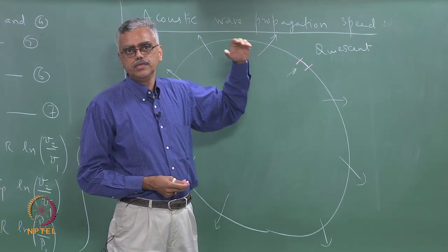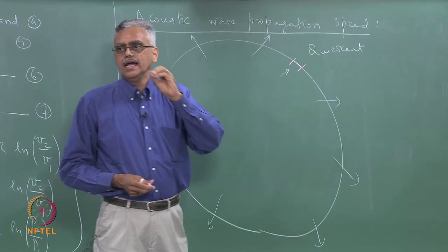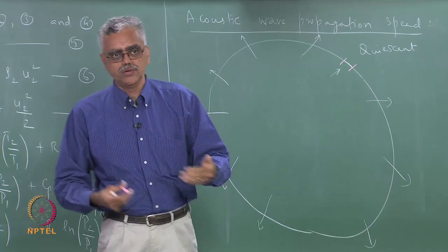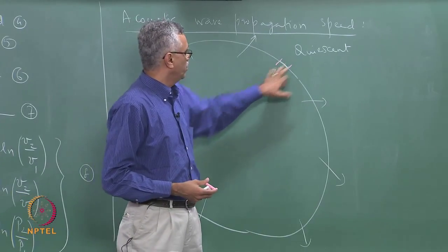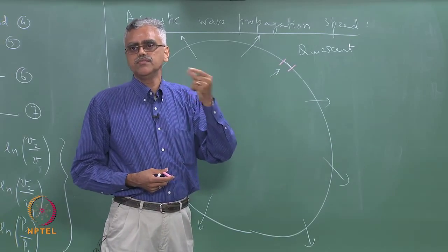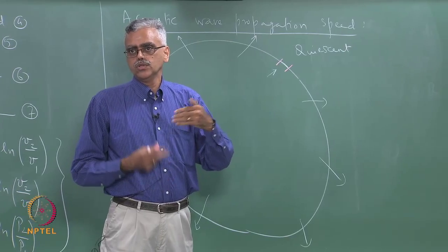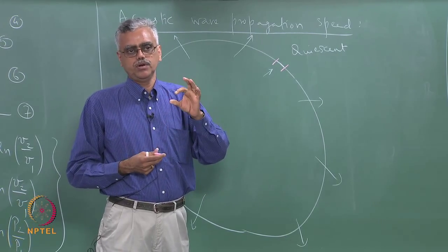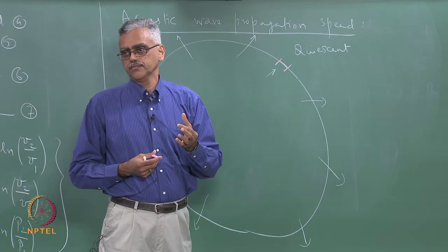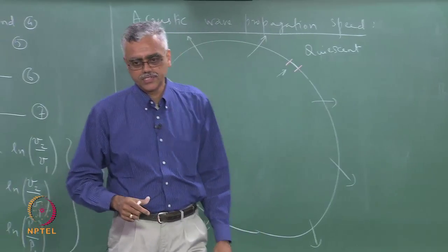Okay? So we are looking at a very special case where this wave imparts only an infinitesimal change in the properties of the fluid through which it passes. In other words, once it passes through the quiescent fluid, the pressure becomes infinitesimally more, temperature becomes infinitesimally different, velocity becomes infinitesimally different. So the passage of the wave and the change in property, the process through which this occurs is an isentropic process. Okay? This is the scenario that we have depicted in this figure.